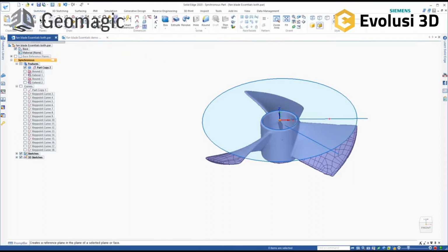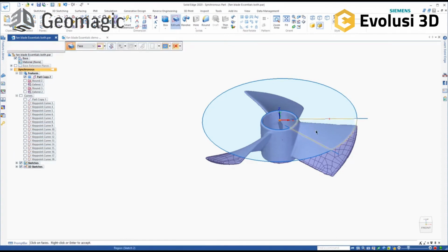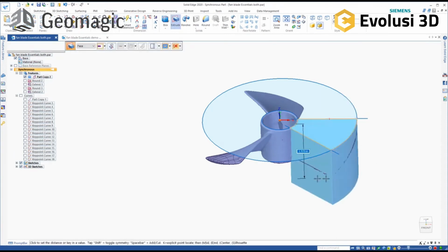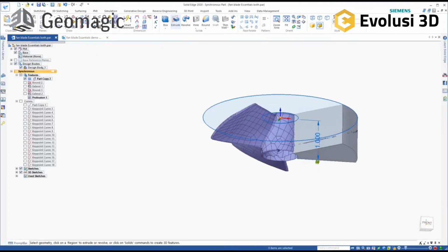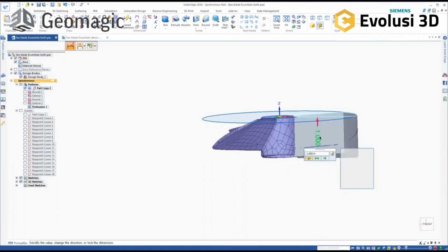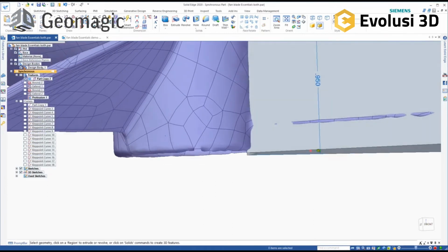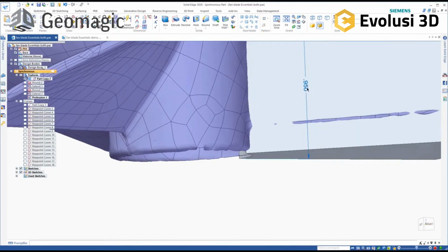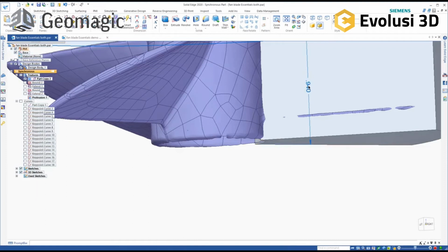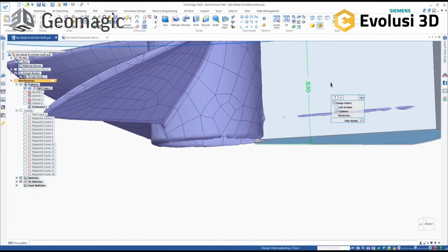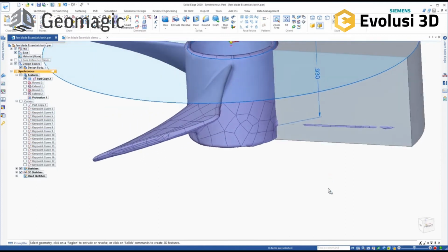just using that profile and select what loop that I want to use. So if I come over to click on this area right here and accept it, and then let's extrude this 1 inch. So let's actually edit that and do like 0.95 there. And you see, you can use that as a reference to see. And make decisions reverse engineering how I want to.